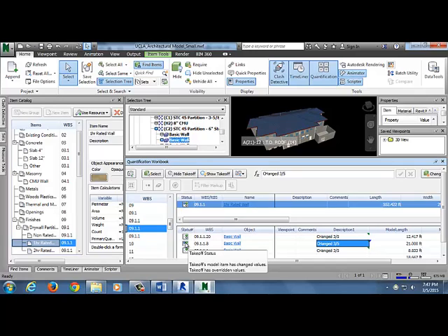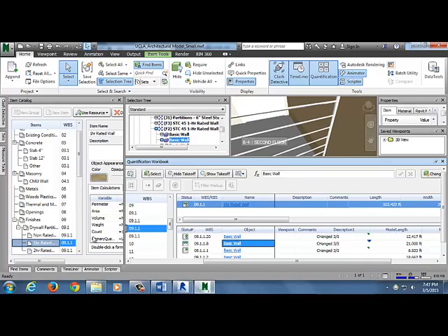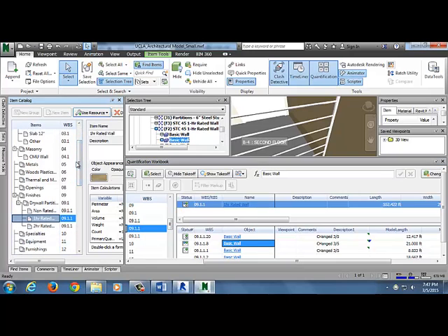So in my experience, this works really well for going through each change. It forces you to go through and look at each change because I can't just globally say update model all for my takeoff. I have to go through at least each type. So in one sense, that's super annoying to me because it takes more time. But in the other sense, it's good because it forces you to go through and you know exactly what's changed a lot better.